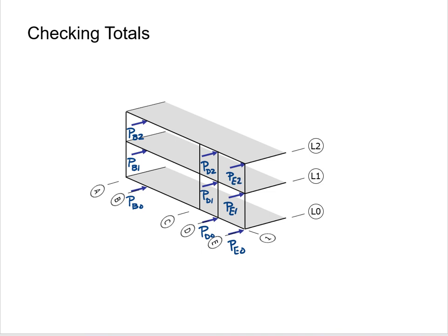As a reminder, the final step in the analysis process is to add up these point forces and compare that total with the total applied load. If they don't match, we can be certain that we've made a mistake. Go back and fix it. In later chapters, we go over how to analyze the lateral elements given the point loads acting on them.